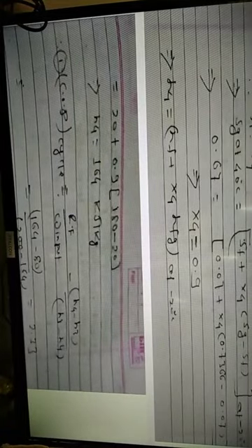Looking at this table, at minus 20, HF is 20, X4 is 0.9, and HFG is HG minus HF, where HG is 180 kilojoule per kg and HF is 20. Simply putting in these values, H4 is equal to 164 kilojoule per kg. So this is the enthalpy at the exit of the evaporator or the enthalpy at the entry of the compressor.